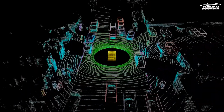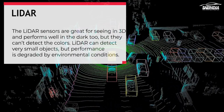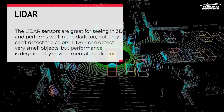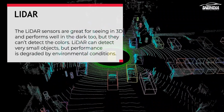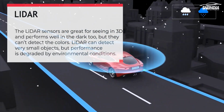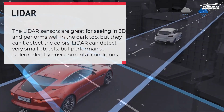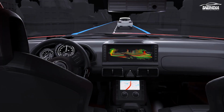The LiDAR sensors are great for seeing in 3D and perform well in the dark too, but they can't detect colors. LiDAR can detect very small objects, but its performance is degraded by smoke, dust, and rain in the atmosphere. They require less external processing than camera systems, but they are also more expensive than the vision sensors.